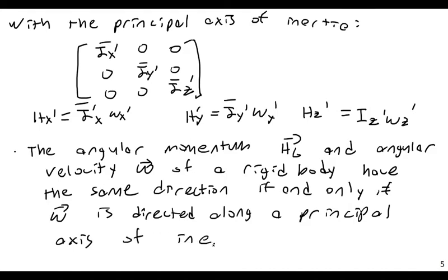And perhaps a better definition of a principal axis of inertia: when you study mechanics of materials, you will hear the term principal stress, and it's the same kind of idea, effectively. If you have a general amorphous 3D body, a very lumpy shape, depending on which directions you consider it rotating, certain planes are going to have a higher moment of inertia in the x, y, and z axes.